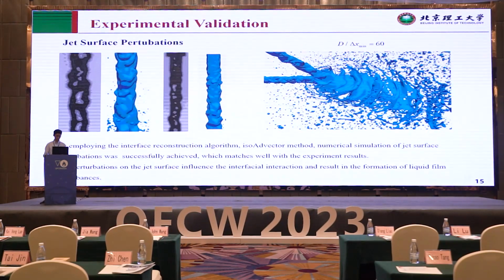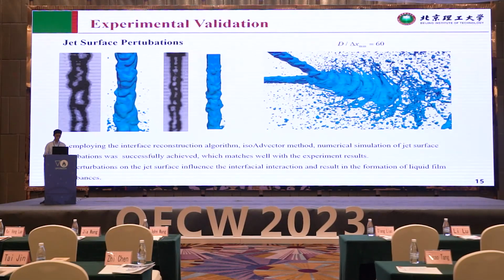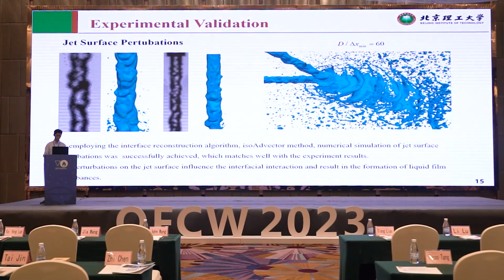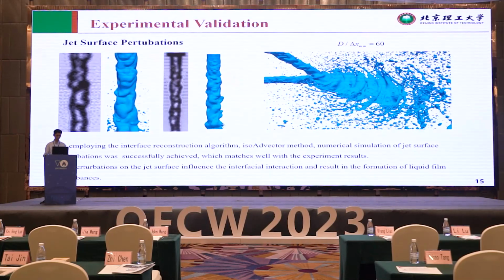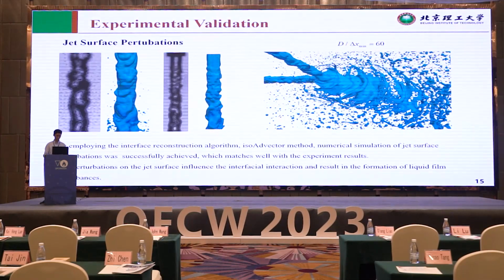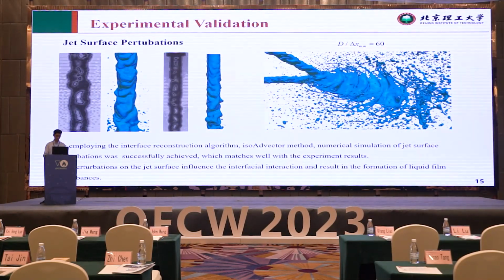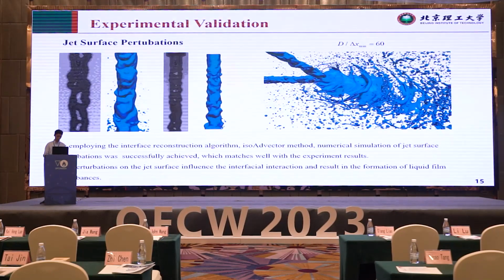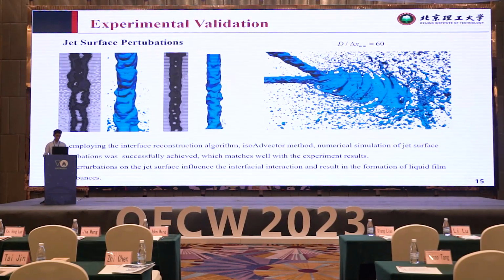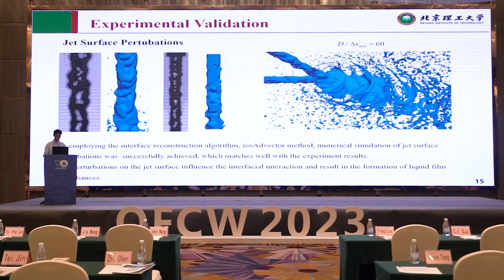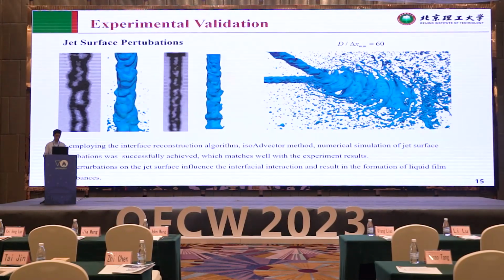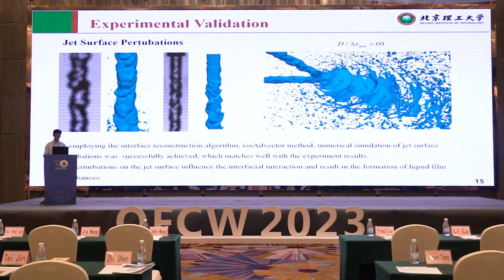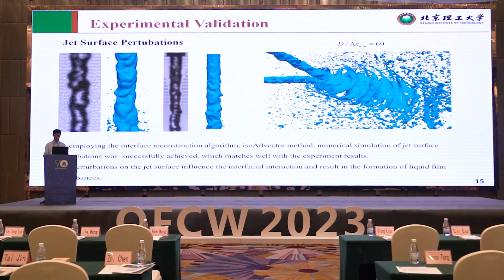Numerical simulation of jet surface perturbation was successfully achieved, where the simulation matched well with the experimental observation by using the interface reconstruction algorithm, the isoAdvector method. The perturbation of the jet surface influences the interfacial interaction, which results in the formation of liquid film disturbance.